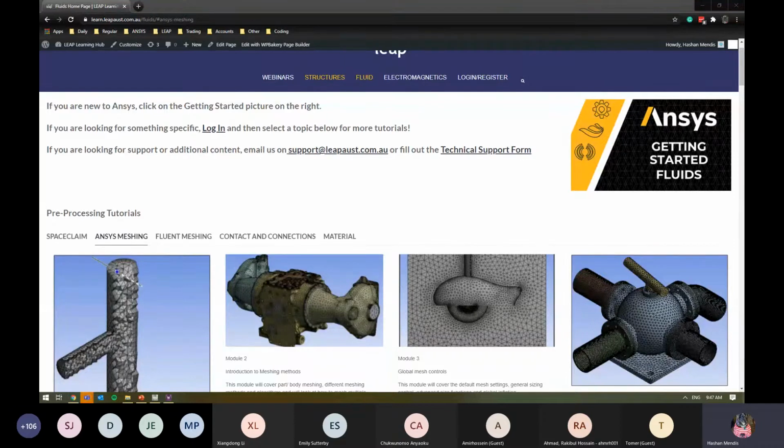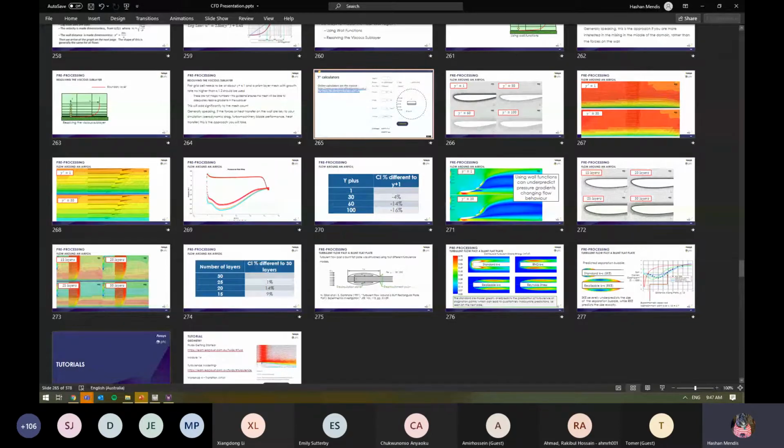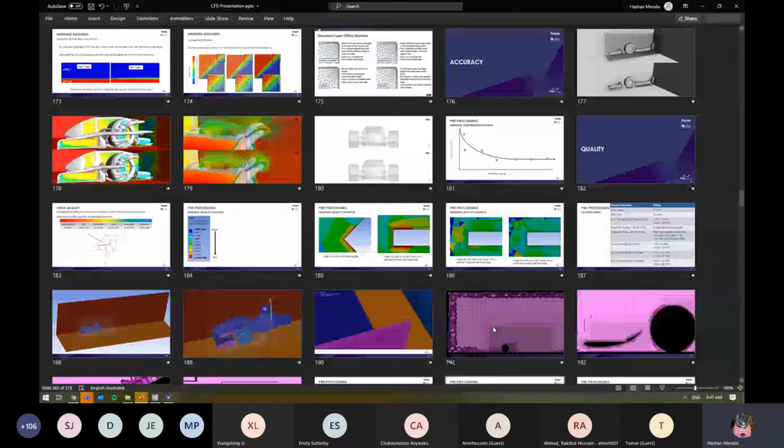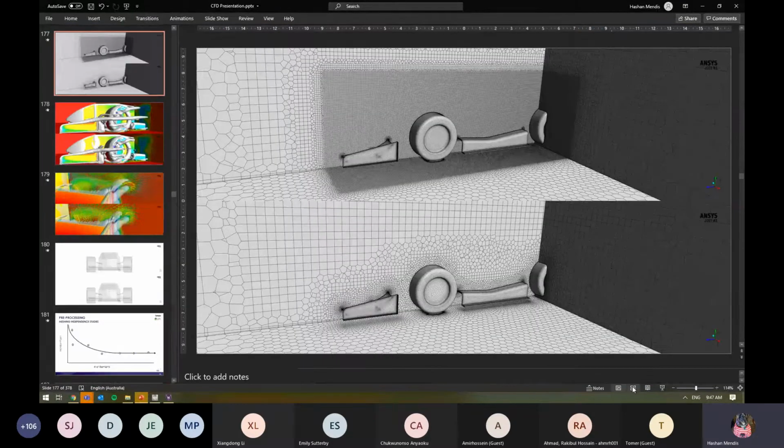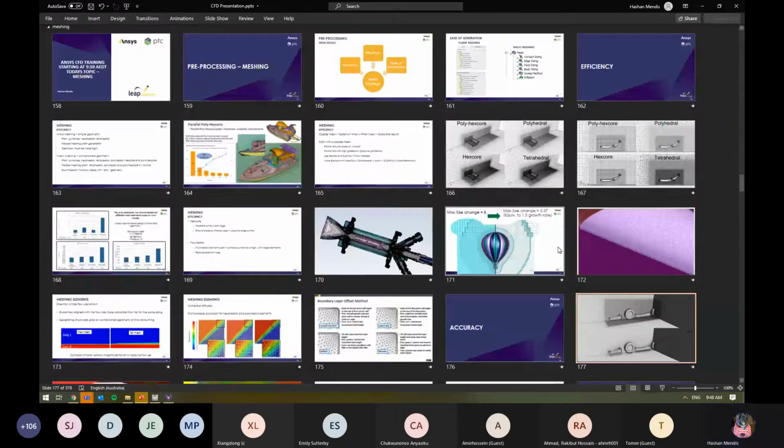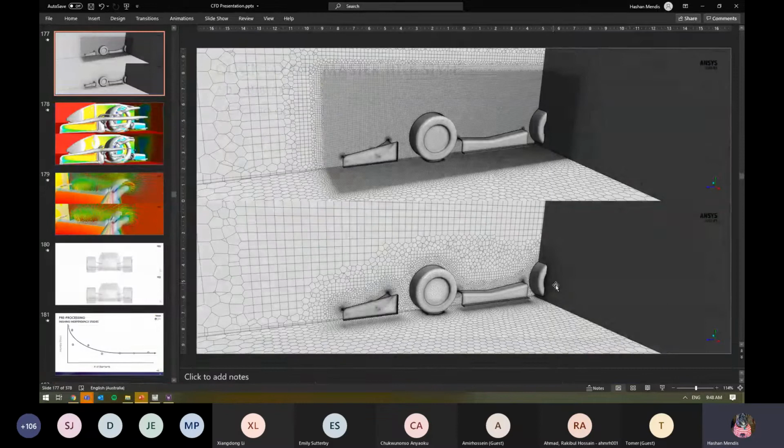So we've got a question about, when you're conducting a mesh refinement study, would you first increase the surface mesh or volume mesh around the area of interest? So yeah, again, there's no one size fits all. So you might need to play around with it. In this example where you've got something like the wing, generally, because the pressure gradients are very high, you'd like to be solving a Y+ of 1. So you need to have a very thin layer and very thin boundary layer. And generally for a Y+ of 1, you might need to have 20 to 30 boundary layers in there as well, right?